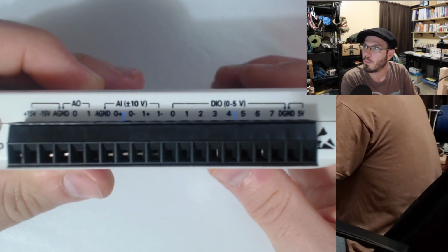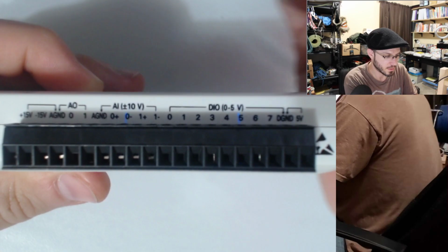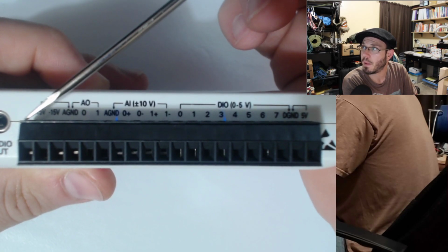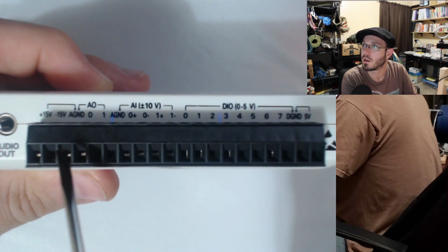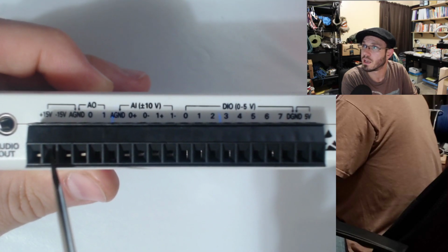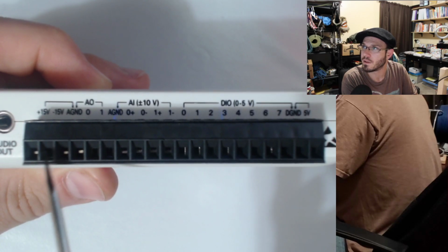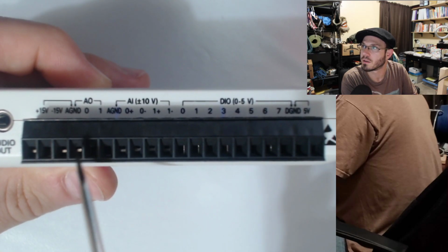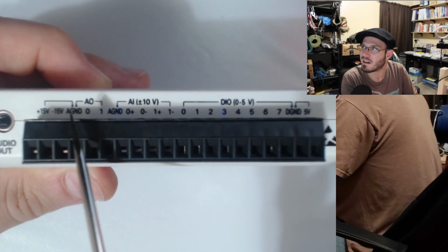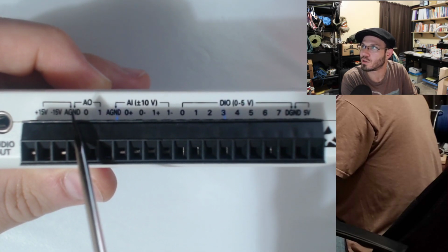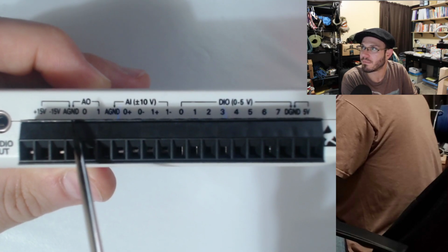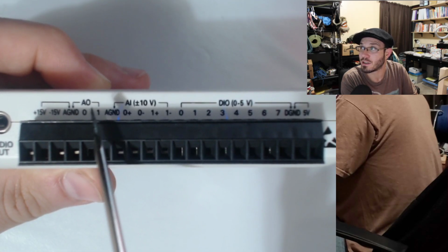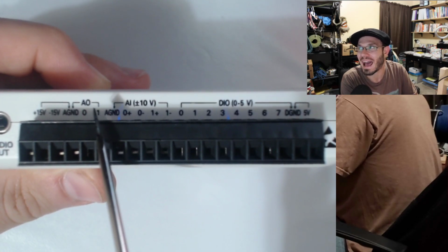Okay, so I'm looking from left to right. And over here we have one connector for plus 15 volts. That's for our power supply. We also have the next one over, which is for minus 15 volts. And that's also written at the top right here. And so that's the second connection. And then we have 2 pins for ground. And they just put an A there to signify analog ground as opposed to a digital ground. They're all going to be the same for us. Analog ground, these two. And then we have A0, or I should say AO for analog out.